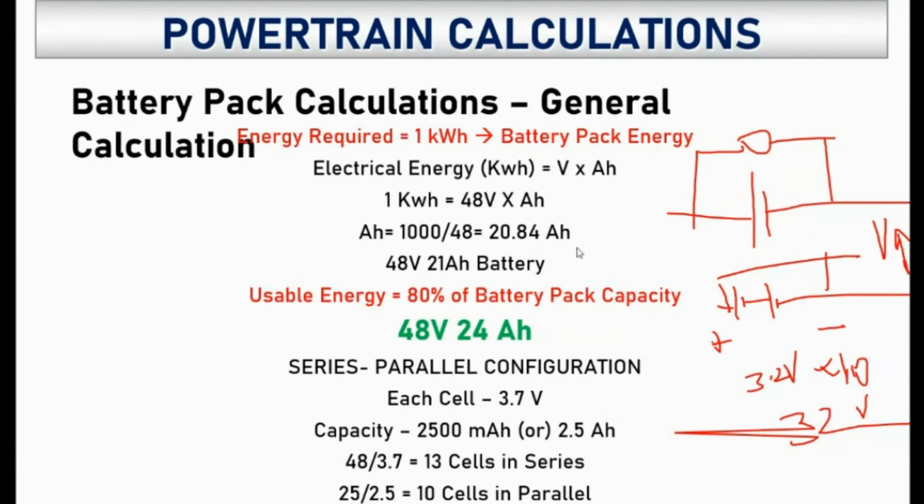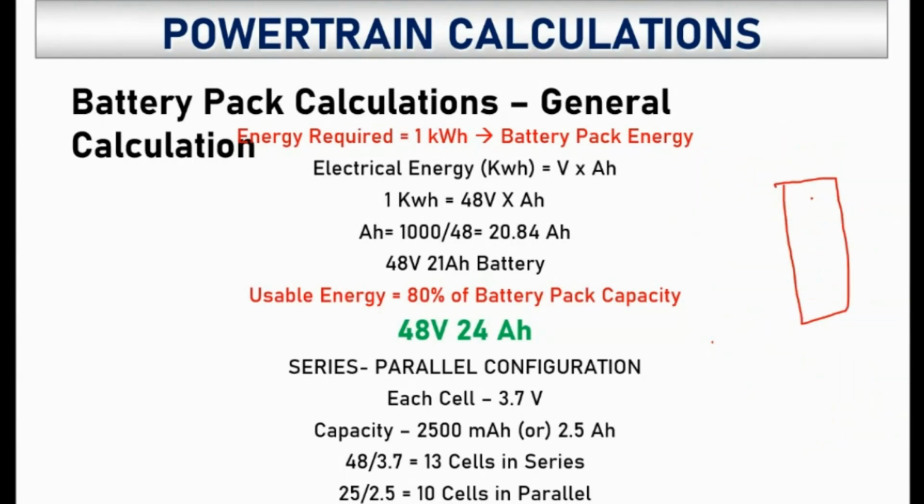So we now go back to look at what is available in the market. Many times it can be like 21, 24, and it differs between different suppliers. But do you know that the usable energy of a battery pack is just 80%, or even lesser than that? Do you know that? Why? Even in your mobile phones, for any devices that have batteries. You are probably familiar with this terminology, SOC, and we also have DOD, depth of discharge, which are quite similar, both of these terminologies.